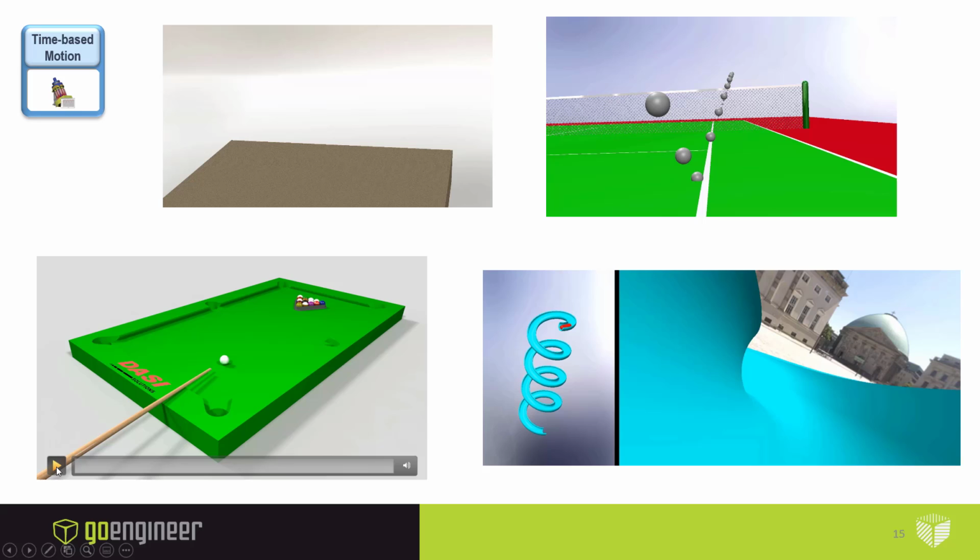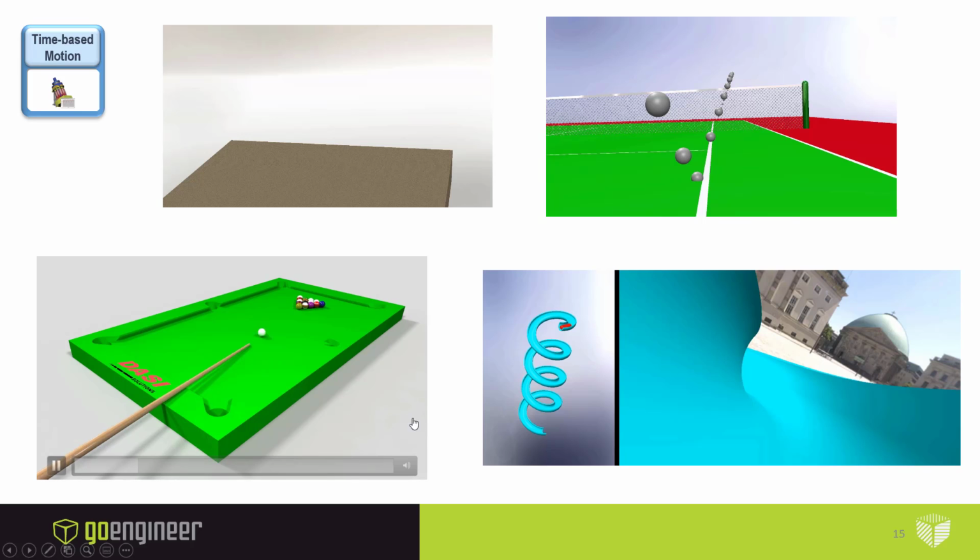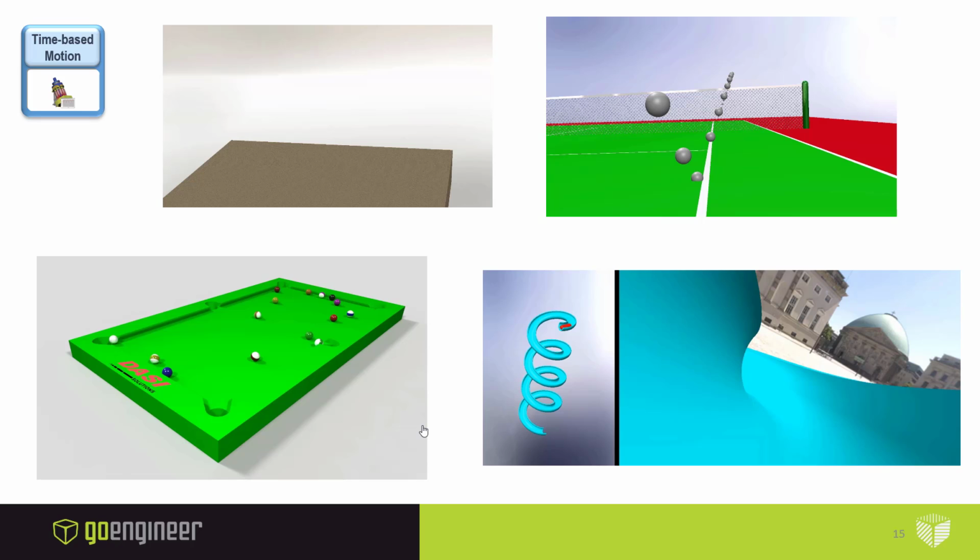Another contact example is just a billiard ball. Now what's special about this one? It's a lot of contact, but really it uses the photorealistic rendering tool, PhotoView 360. You just turn on a little switch when you go to save the animation that you created, to tell it to use the photorealistic renderer, and it creates a much more realistic looking image. This came right out of SOLIDWORKS. You see the shine on the balls and everything. Now it does take a lot longer to save that because it has to render every single frame of that animation. So this took hours to render.